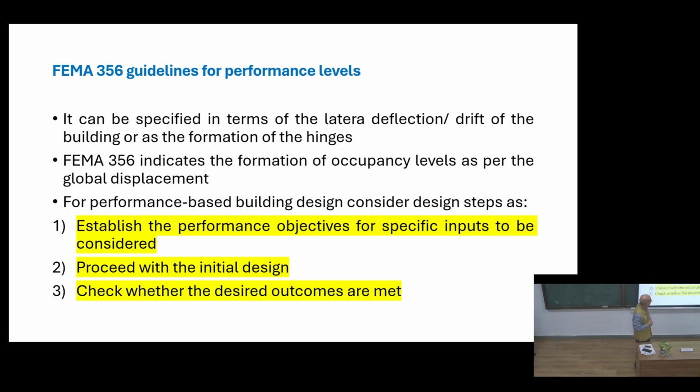But we don't do that much. There are certain things inside that. For a certain purpose, you bring the load down and allow the structure to deform, so a non-linear deformation occurs. That means when you remove the load, it does not regain its original position, and some deformation is left in the structure, and that is acceptable. We'll talk about how it comes into the picture. So these are certain performance levels you fix, and deflection is one of them.